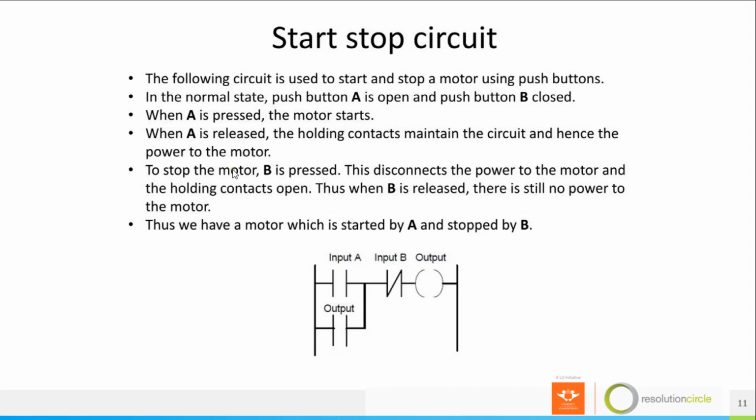When A is pressed, the motor will start. When A is released, a holding contact maintains the circuit, hence the power to the motor.